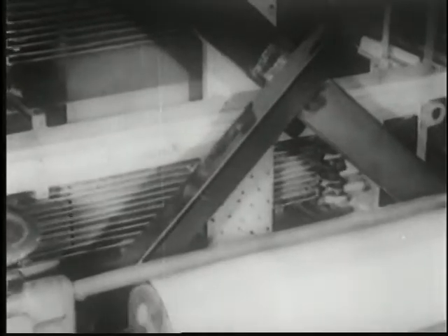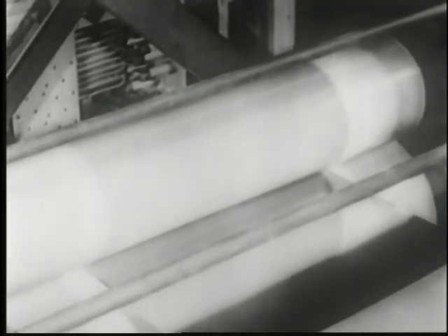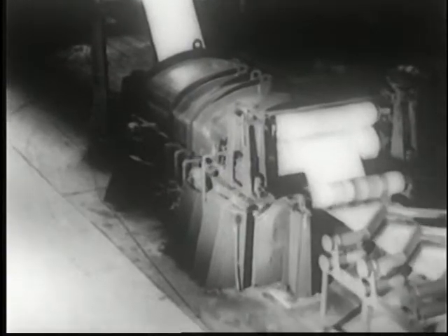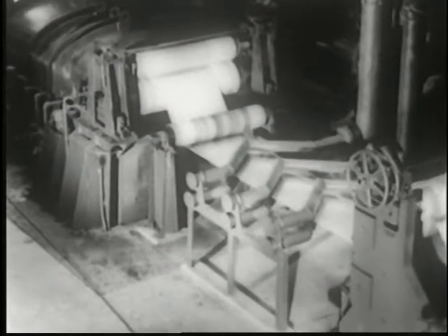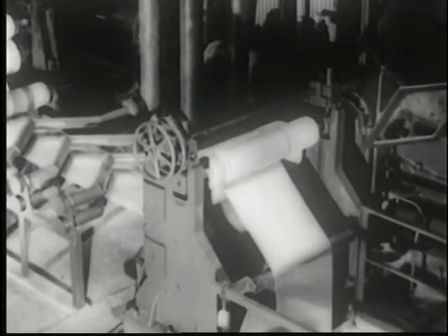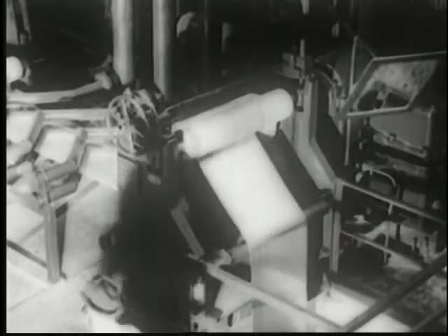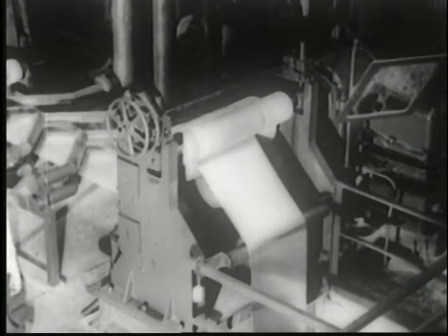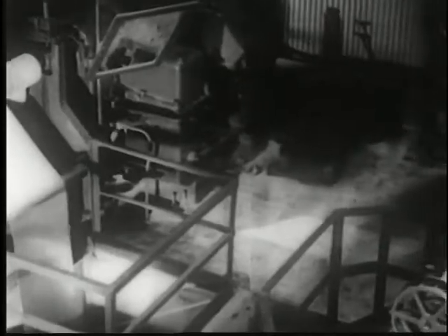Here is a new, less familiar application of electronic high-frequency generation. High-frequency heating of 200,000 cycles per second is now used to flow tin as the final step in the electrolytic plating of steel strip. After steel strip comes from its electrolytic tin plating bath, it first passes through a washer, then between hot air drying jets. At this point, the steel strip has a coating of tin that is relatively dull and porous. Next comes a vital step.